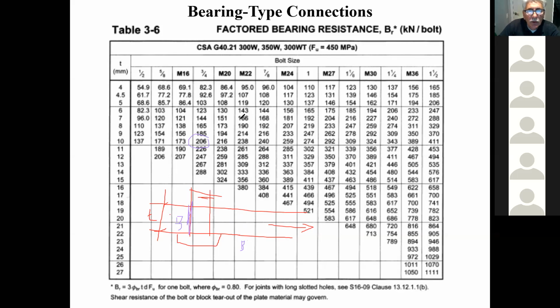So this table very quickly gives you the values. Sir? Yes. Does this apply if this was wood being bolted? Are these the same values? No. This is steel on steel. Steel on steel, okay. Andrew, not only is it steel on steel, it's also this strength of steel. There are different tables for different strengths.